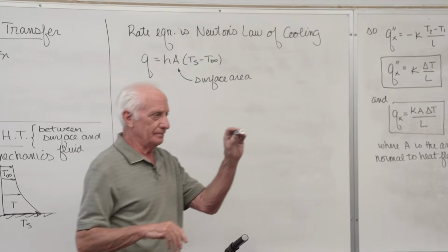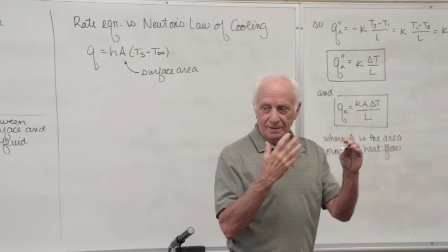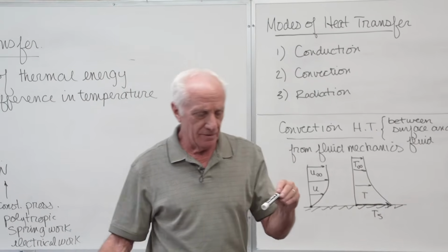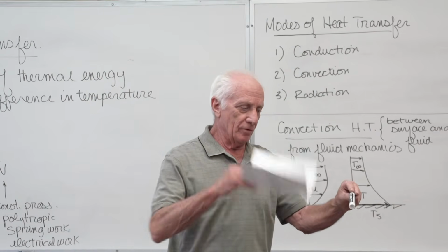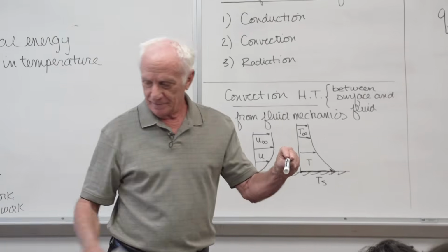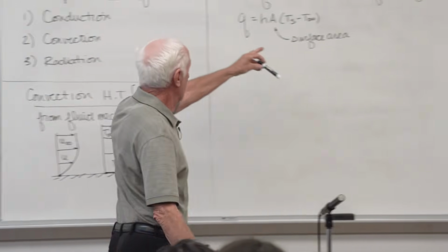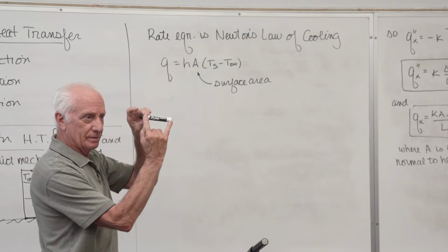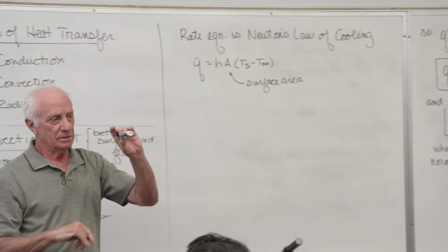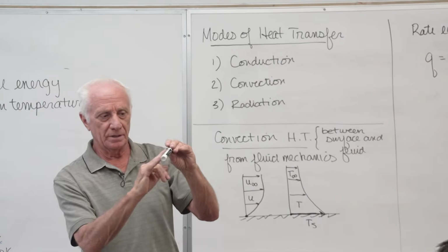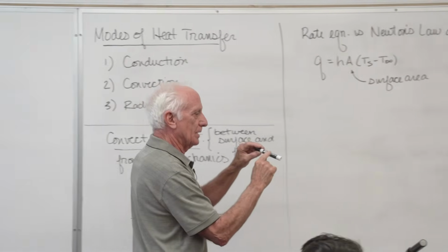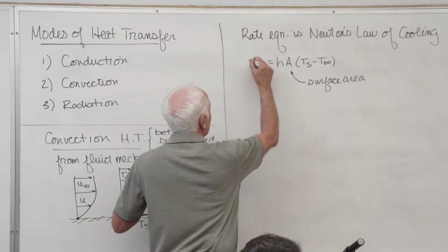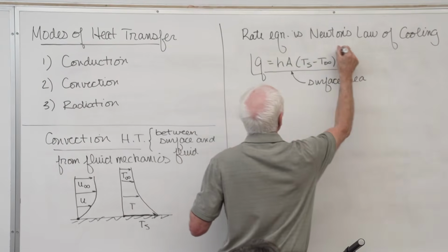Take that pen. The pen's hot. The air in this room is cooler. Convection heat transfer. I blow air over it. There's the equation. What's the right area? Pi d times L, there's L. That area, pi d L, okay? Pi d, circumference, L the length. Where does the air touch the fluid, or touch the surface? That's what it means. So that's our basic convection equation.